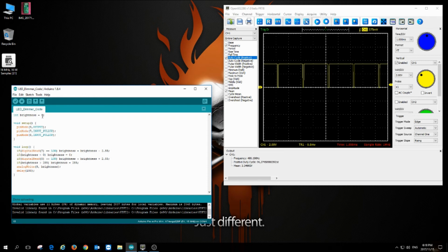And then if I come down again, or if I push and hold the down button, you can see how it slides through. So now what we got is basically a varying DC mean voltage, which we can use to control the logic level gate on the MOSFET. Try and pick a logic level MOSFET to get this done. I don't really have any, so I'm having a bit of an issue trying to find some. As soon as I do, we'll put this into practical applications, but there, for all practical intents and purposes, you can see it increase and decrease.